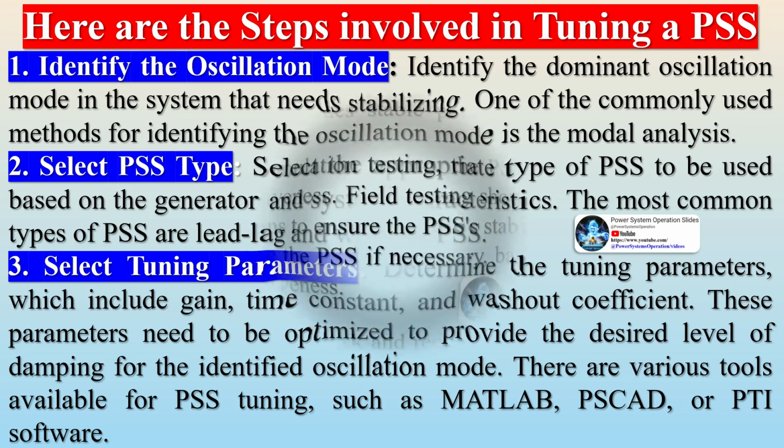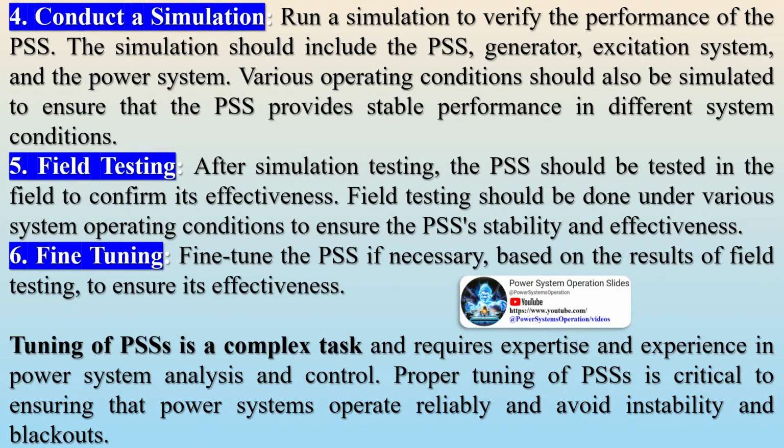Conduct a simulation. Run a simulation to verify the performance of the PSS. The simulation should include the PSS, generator, excitation system, and the power system. Various operating conditions should also be simulated to ensure that the PSS provides stable performance in different system conditions.